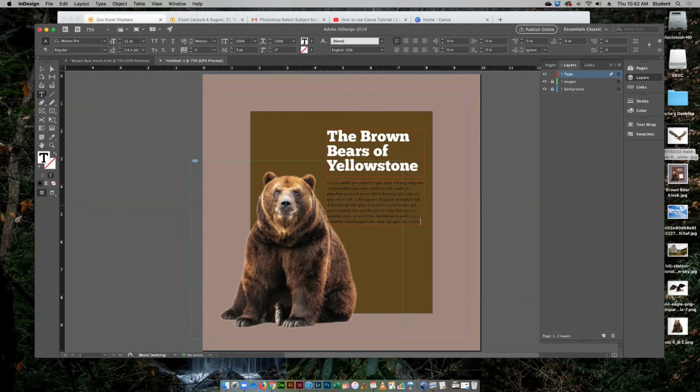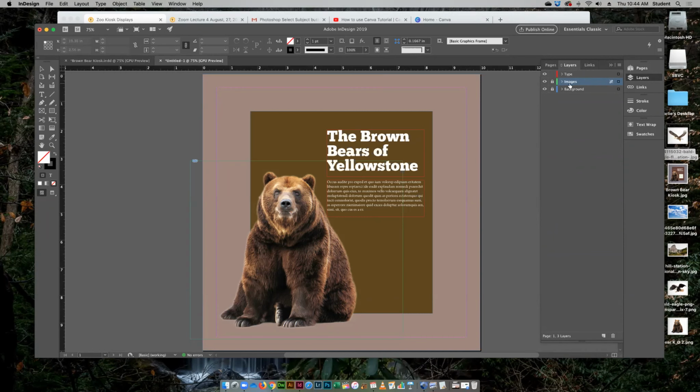And I'm going to grab my Yellowstone map, and I'll give this to you also. And I'm going to click Open. Okay. I've got this little pencil here that has a can't place icon on it. Why? Because the layer is locked. I forgot to unlock this image layer. So I have to unlock this image layer, and now I can place my map.